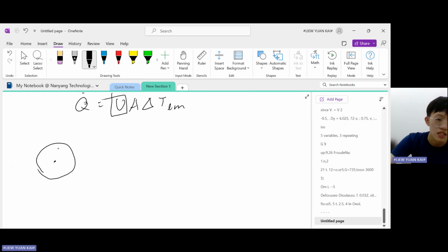First, inside this cold water pipe, there's convective resistance, because it is heat transfer to a fluid. Then outside, there's steam, which is also a fluid, so we have convective resistance there too. So this is the outer convective heat transfer, and the inner convective heat transfer.